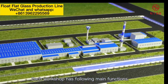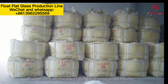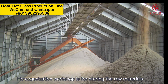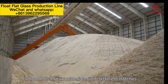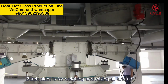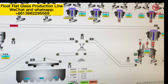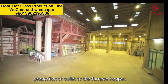Each workshop has following main functions. Raw material storage is for receiving and storing qualified raw materials. Homogenization workshop is for storing the raw materials as well as homogenizing the moisture and chemical components of raw materials from different batches. Batch plant is for weighing and mixing all kinds of qualified raw materials per formula and conveying qualified batch with a certain proportion of cullet to the furnace hopper.